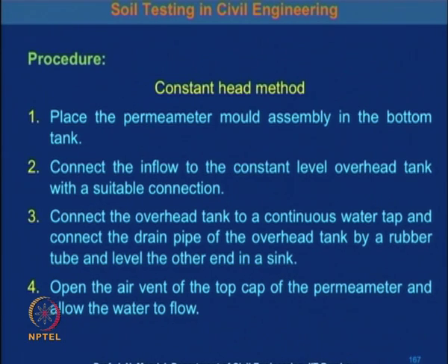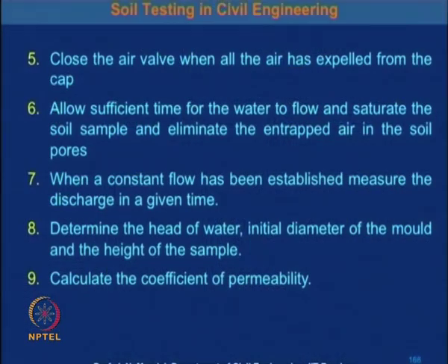Open the air vent of the top cap of the permeameter and allow the water to flow. Next, close the air valve when all the air has been expelled from the cap. Allow sufficient time for the water to flow and saturate the soil sample and eliminate the entrapped air in the soil pores.